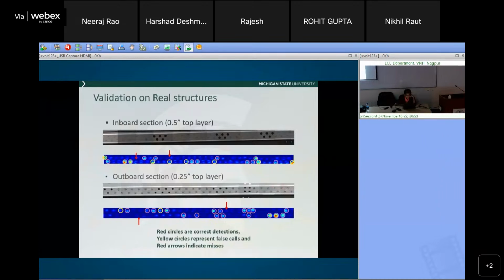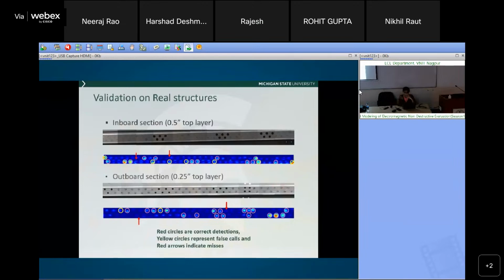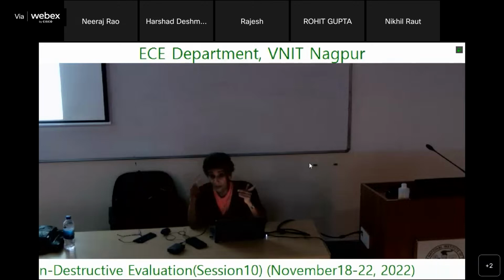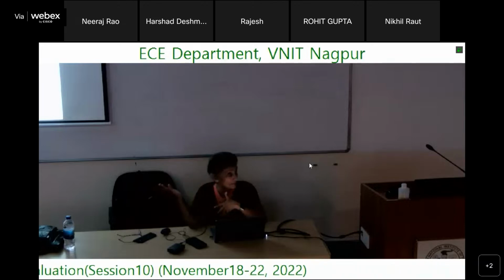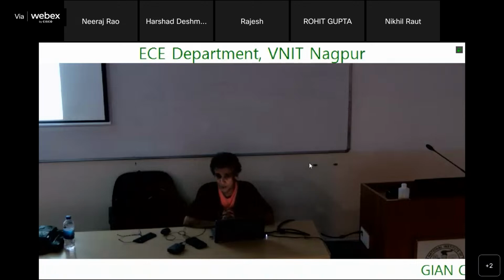How did you model the GMR? Well, for GMR, we have the characteristics. When I talked about it in the eddy current lecture, the characteristics of the field to voltage, or resistance, is known. What we measure is a function of the resistance of that. We can directly convert the resistance into field. So that is known for any particular GMR sensor.